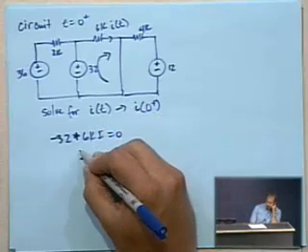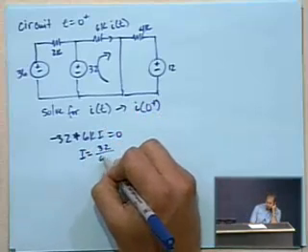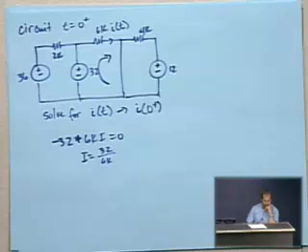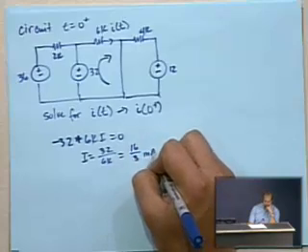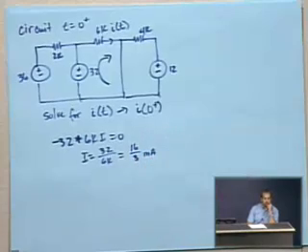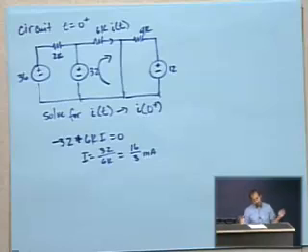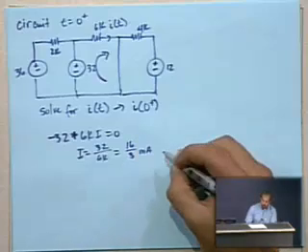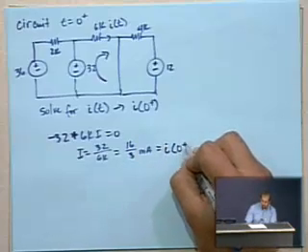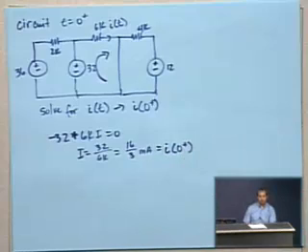And so I equals 32 divided by 6K, which is the wonderful number of 16 over 3 milliamps. You'd think that as long as they were picking these numbers, they could pick them to be somewhat more intelligent instead of 16 thirds, but whatever. So that is I of 0 plus. We set that aside and say we will use that again because we need that for our constant K2.